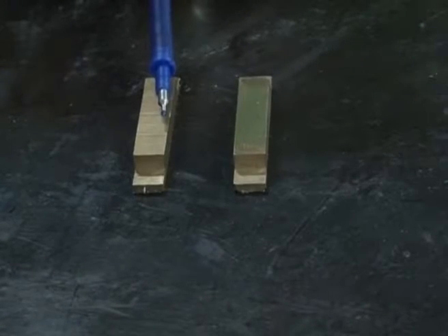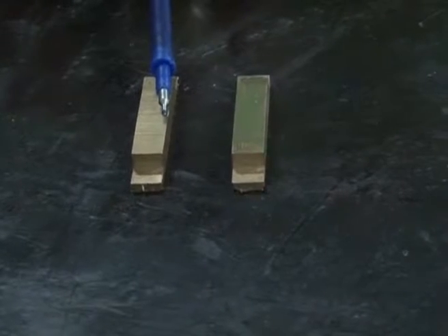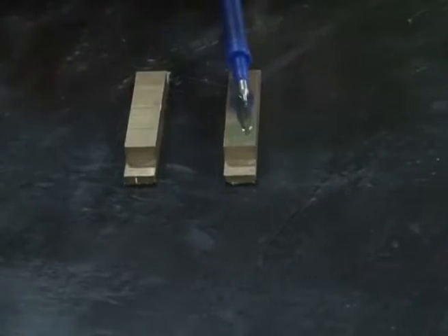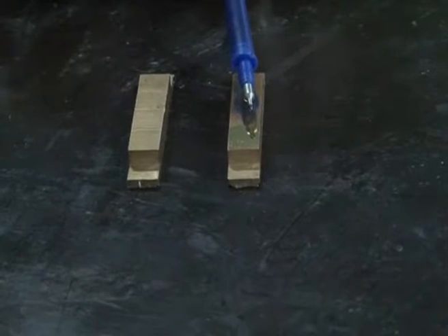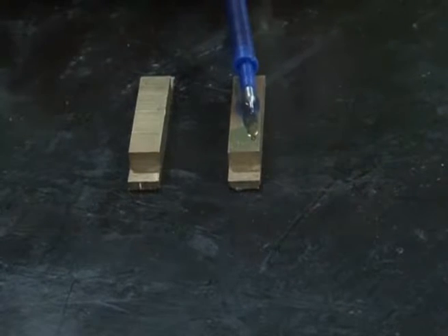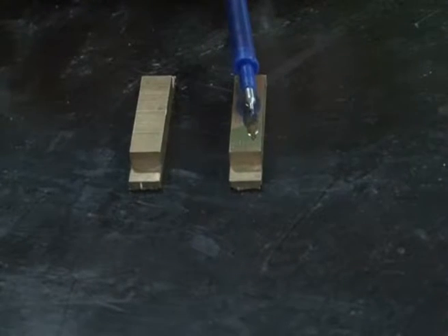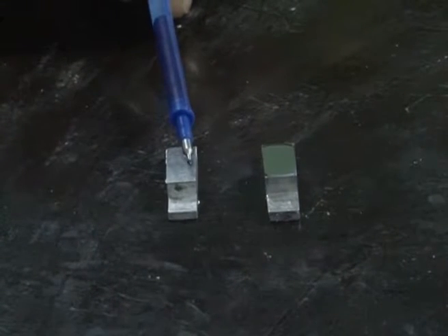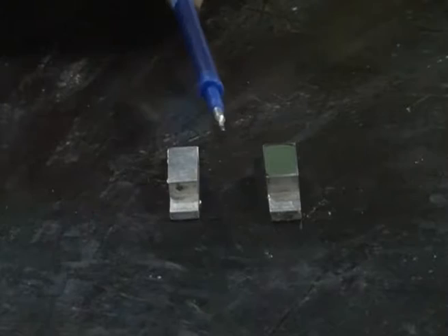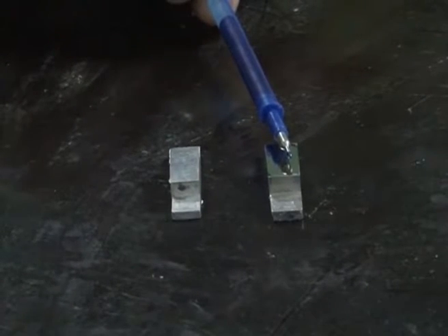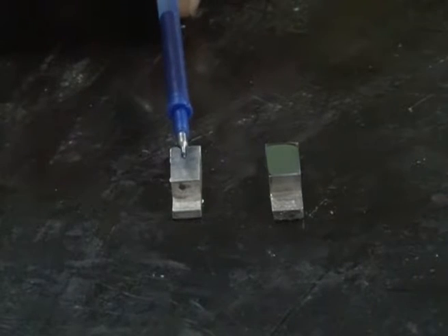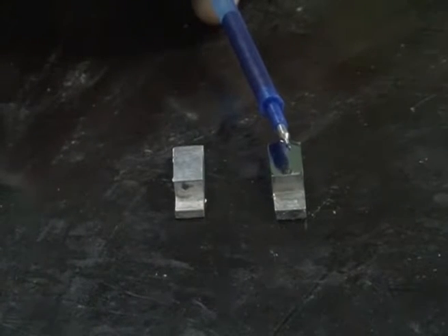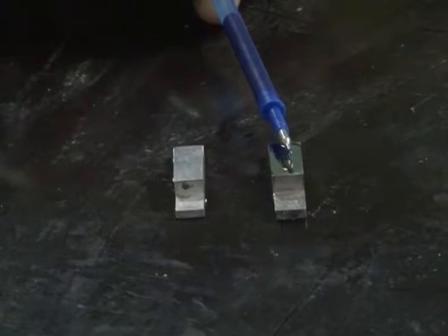You can see the initial workpiece of the brass, wherein you can only see the shadow, but you cannot see any mirror image, whereas you can see the clear image or the mirror image in the finished surface by using rotational abrasive flow finishing process or universal rotational abrasive flow finishing process. You can see the aluminum metal matrix composite, wherein you can find only the shadow, but after finishing you can see the mirror image clearly. This is the micron size surface roughness and this is the nano surface finish, wherein we have achieved the best surface finish about 70 nanometers.